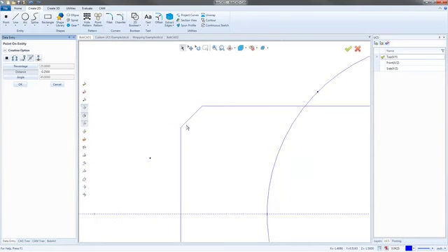And what we'll see is because I clicked on this side, so really what we need, let me put, oh, look, we could just do this right there. Ain't that convenient? So we put a midpoint on it. So that midpoint there is the determining factor on whether or not we get a point to go out this way or out that way, because it just is whichever side of the midpoint we're on. So if I click over here, I'm on the right side of that midpoint, it's going to extend it out.